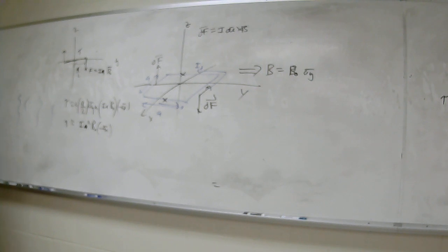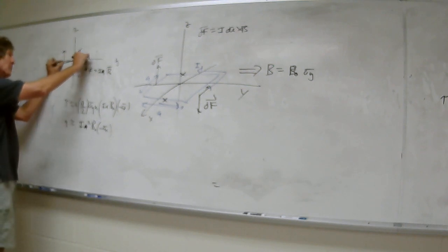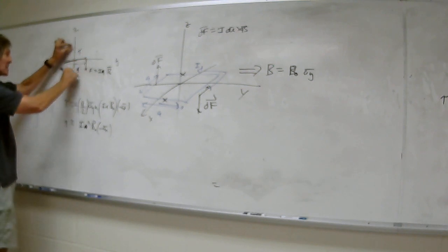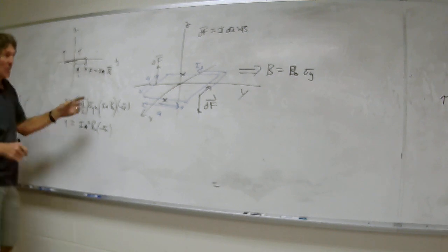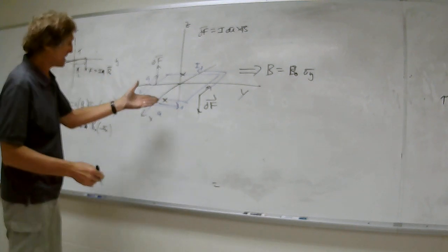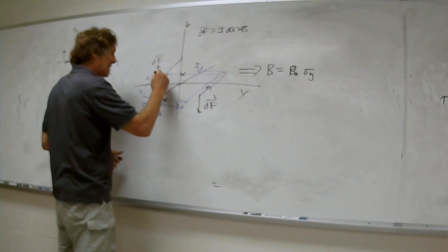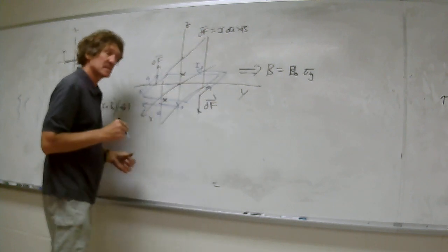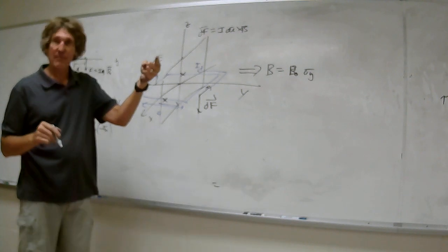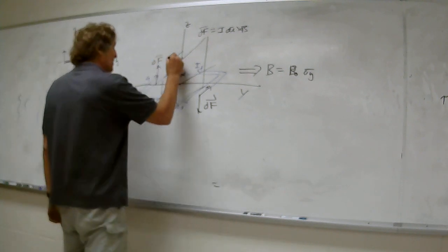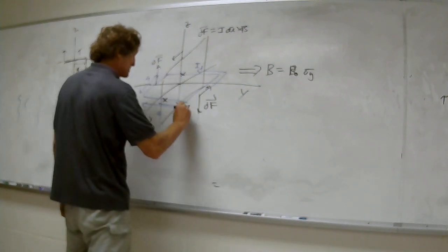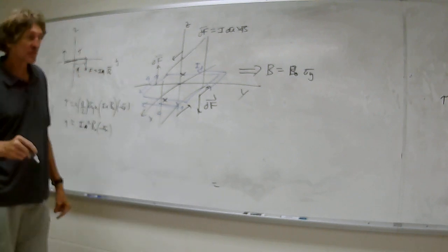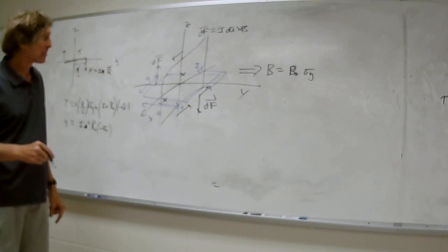Now, something I'm going to mention. Oftentimes when they talk about torque, that's the torque. This is the peak torque. If this thing's allowed to rotate, it's going to rotate, right? Well, what happens when it rotates by 90 degrees and the actual loop is like this? Now, the B field's that way, right? We still have a current going this way and a current going this way. But just think about it for a second. It's going to become very clear.